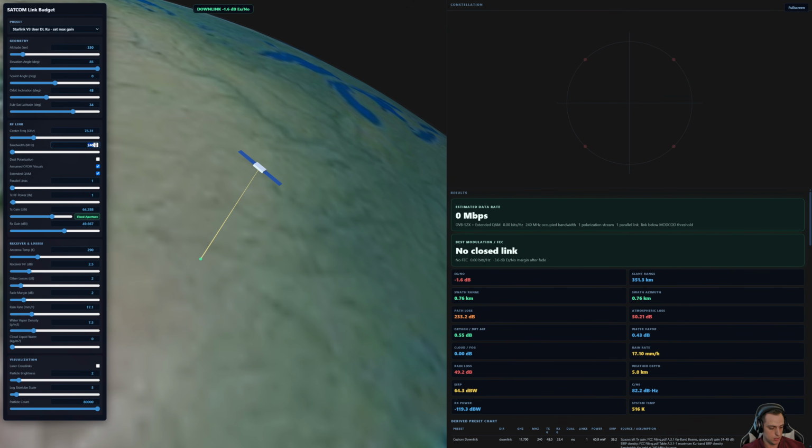First of all, you could just simply increase your power to restore your signal. Alternatively, you can decrease your bandwidth, and that will focus more energy into a smaller bandwidth range, and that will also mean less noise bandwidth. So that will allow you to restore your signal even if you have a severe atmospheric loss. However, at 50 decibels, that means 99.999% of the energy is being blocked. So very few links will be designed to have this much margin, and so we will treat this as our practical limit.